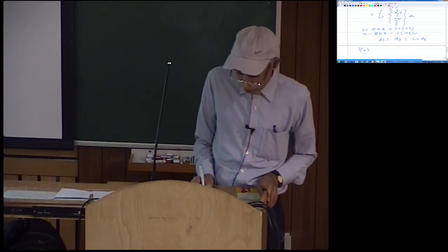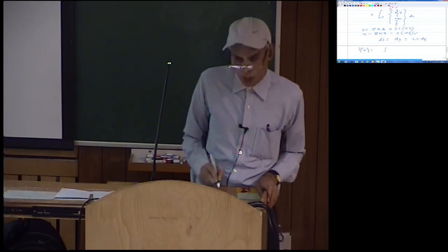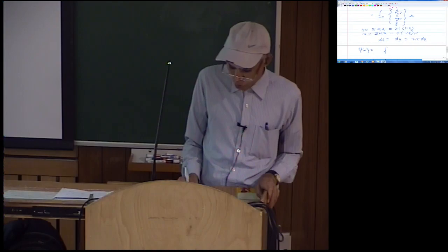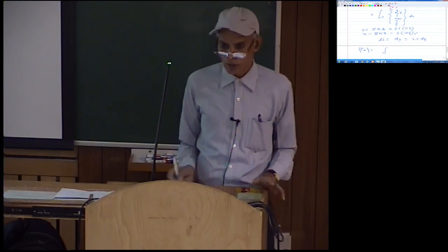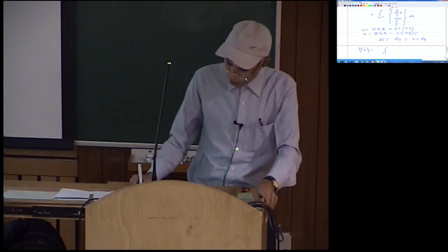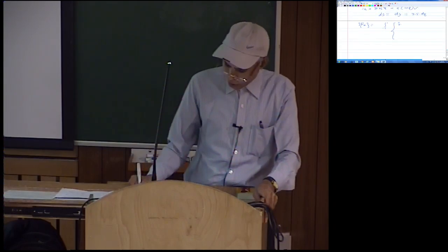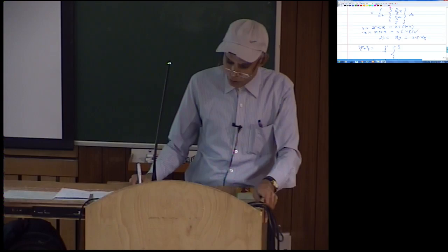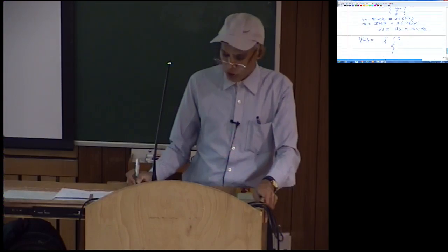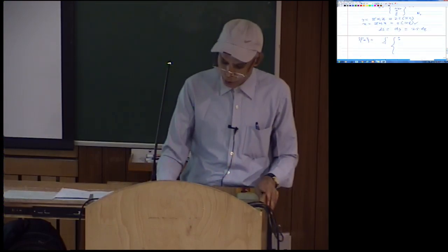So finally you will see that this load vector for the element along edge 2 to 4 would reduce to an integral with eta going from -1 to +1. Now everything is written in terms of eta. Then you have 0 0, that is the first two terms, then N2 into y. Now what is the expression for N2?